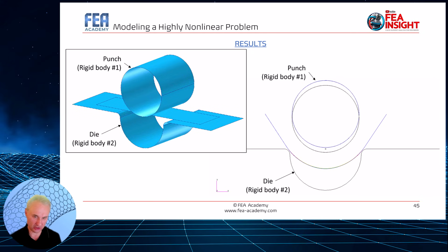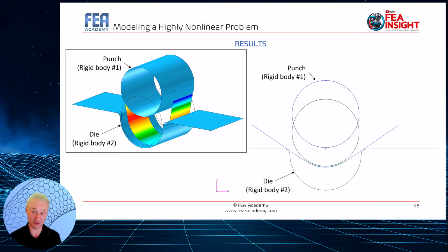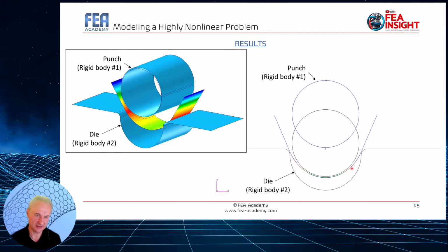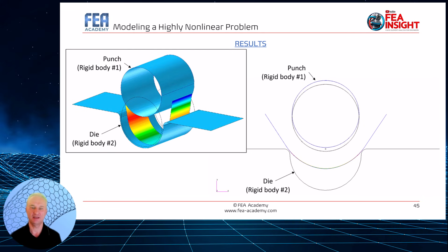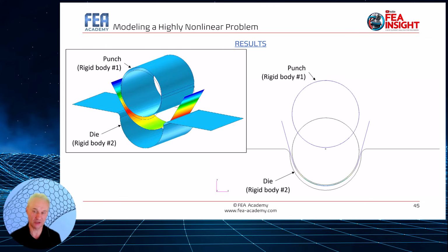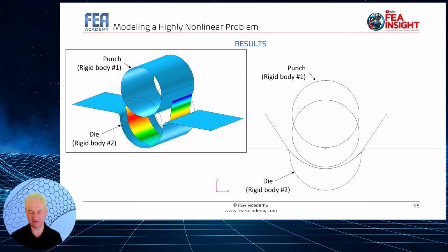During the unloading, the punch and the sheet move simultaneously in an upward direction by remaining in contact. Look again. You see it goes up, it remains in contact, okay? And after that, the punch continues traveling up while the sheet remains in this position. Then the sheet stops moving while the punch continues to move upward to return to its original position. This release of the sheet from the punch allows the sheet to spring back to its final position.